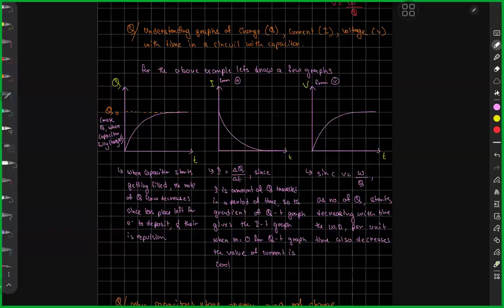Over here, initially, for one thing, if I'm, let's say, storing 100 coulombs of charge, the first 1 coulomb of charge, when going to the capacitor's plate, is not feeling 12 volt, but, let's say, 0.1 volt potential difference.